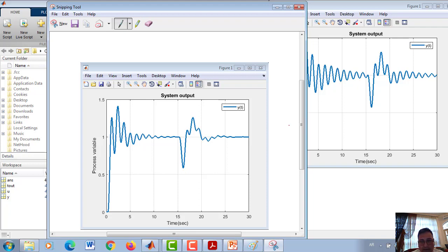For discussion on the last notes, the proposed modified Smith predictor has three controllers: GC1, GC2, and GC3. In addition, a low-pass filter. This low-pass filter is used to achieve improved robustness in both the works, and tuning rules are derived using the direct synthesis approach. This is the main advantage of using the direct synthesis approach. However, the control structure considered in the literature work is completely different from the proposed control structure.